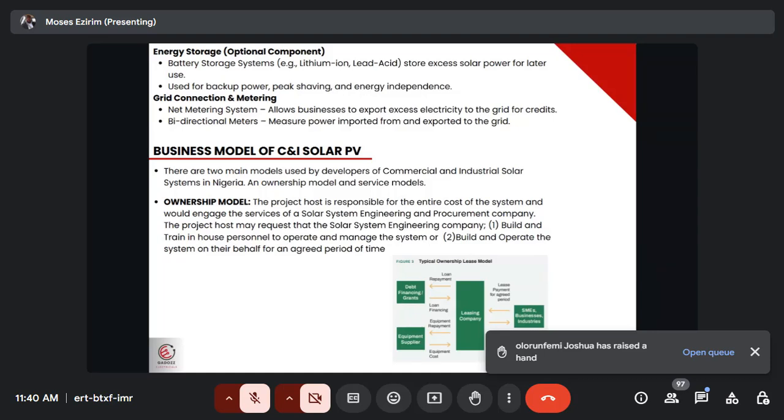Now if your generator should go off, and your PV is still generating, the voltage that is coming out from the PV can kill or injure the operator of that generator.